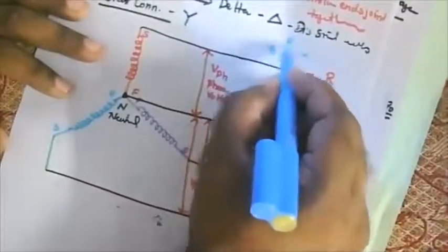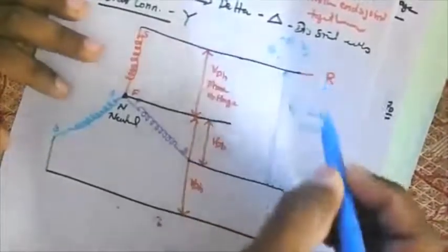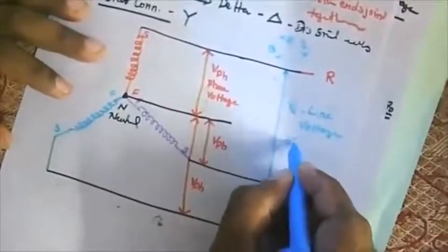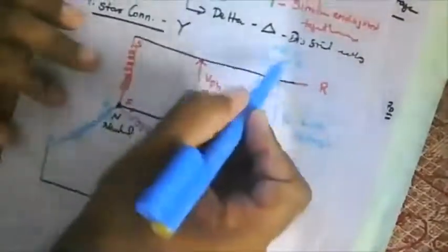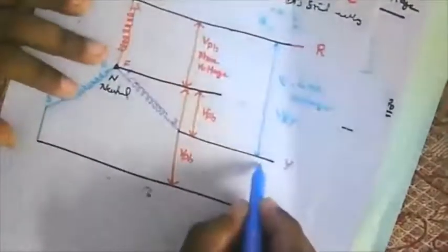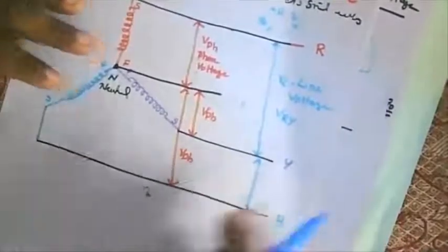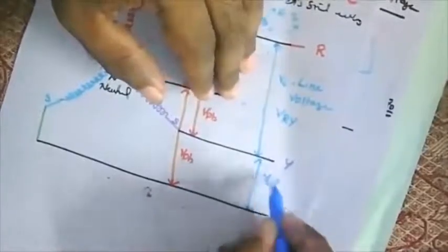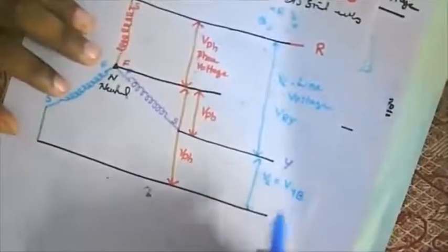There you will have to look into your sequence part. It will be R, Y, B in a cyclic manner. So, what will be this voltage? This is across R and Y. So, I can write VRY. You should not write VYR because it is opposite. So, I am going to write VRY. Here also, I am having a voltage. This is across Y and B, means 2 coils are present. This is going to be VL. This VL is going to be VYB, not VBY.